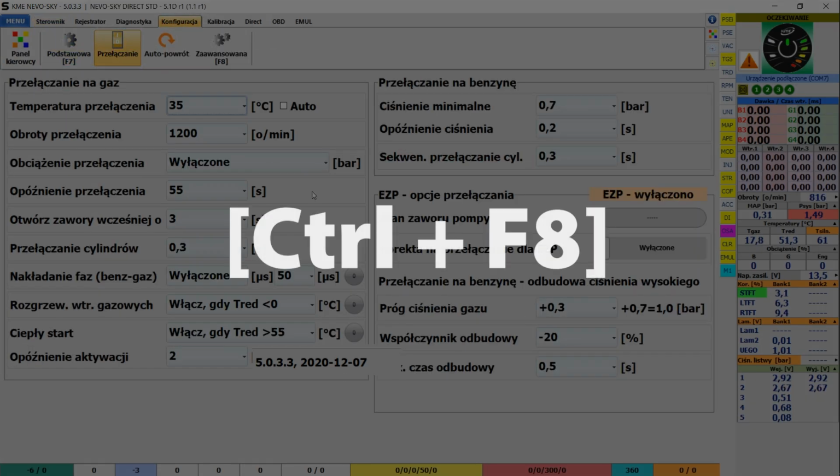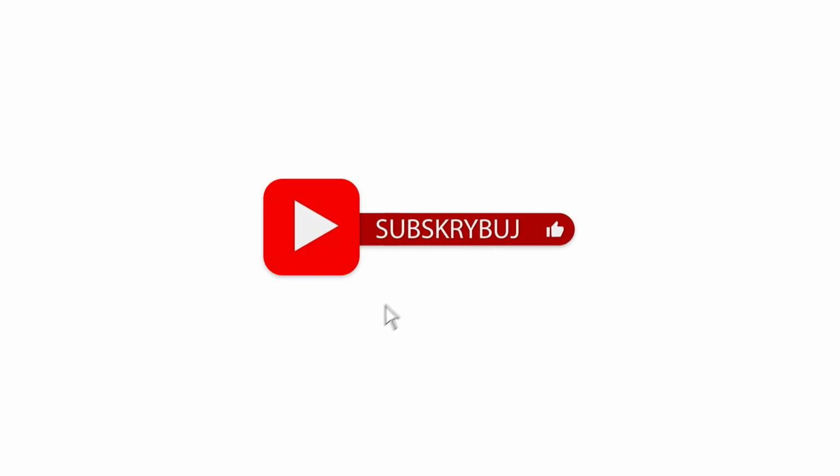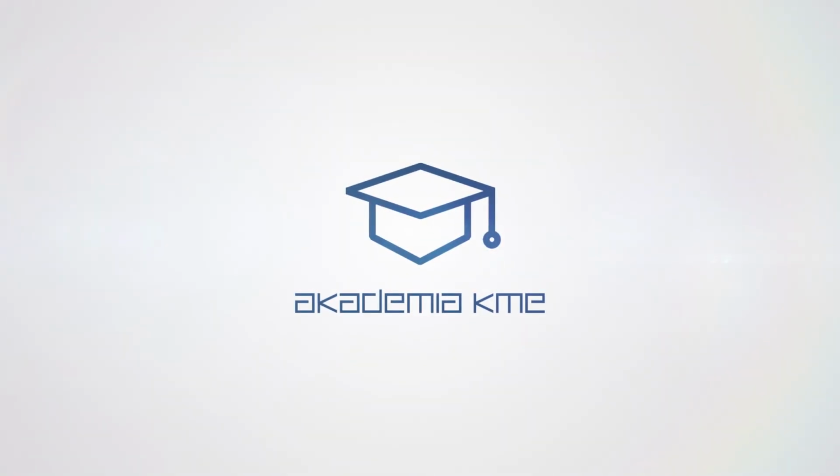The basic parameter is the switching temperature. The system will switch to gas only when the reducer reaches the set temperature, allowing gas to evaporate from a liquid to a gas phase. We recommend using the default value of 35 degrees.